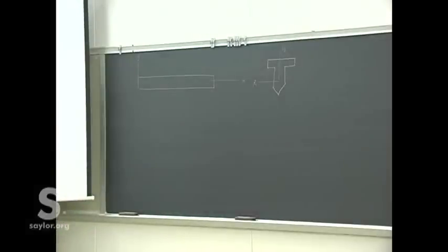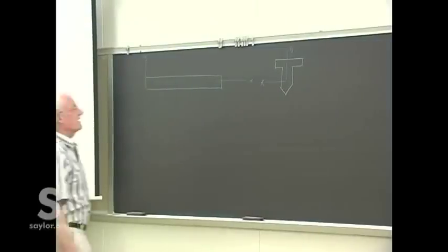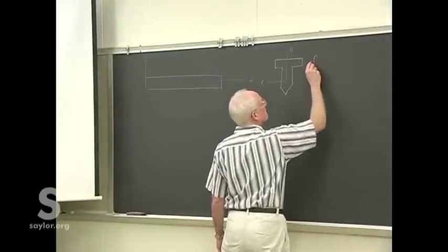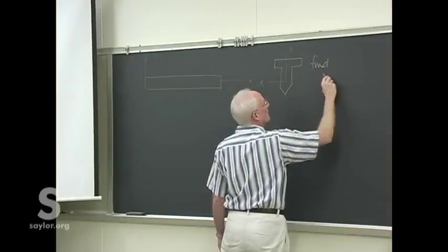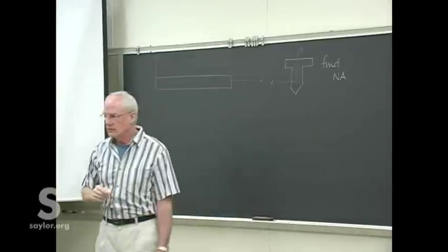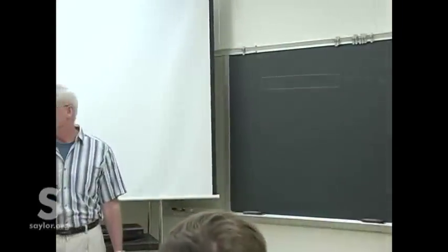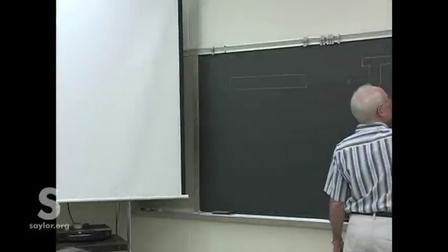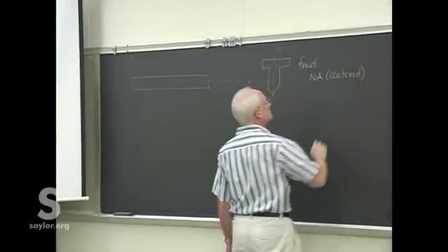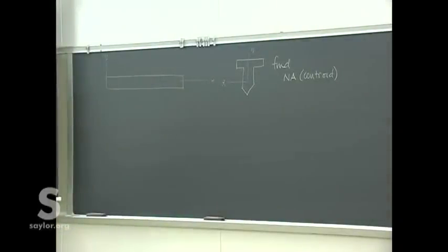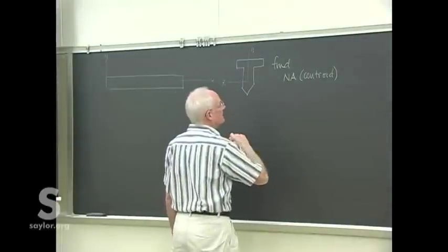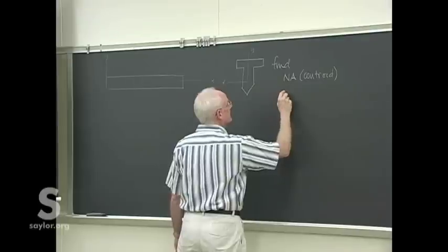And then the only other part of concern with that is, if you remember, we need to find two things with this cross-section now. We need to find what we call the neutral axis, and we'll review in a second why we need that, but it turns out it goes through the area centroid anyway, so it's just a matter of finding the centroid of that area. And then from there, then we can find the bending,